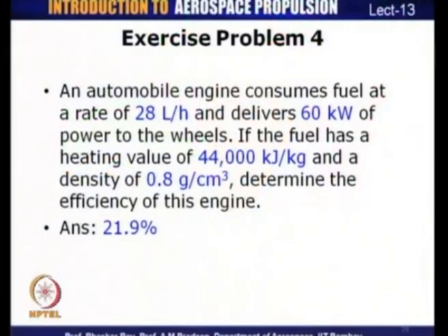The last problem, the fourth exercise problem we have, is that of a heat engine. An automobile engine consumes fuel at a rate of 28 liters per hour and delivers 60 kilowatts of power to the wheels. If the fuel has a heating value of 44,000 kilojoules per kilogram and a density of 0.8 grams per centimeter cube, determine the efficiency of the engine.